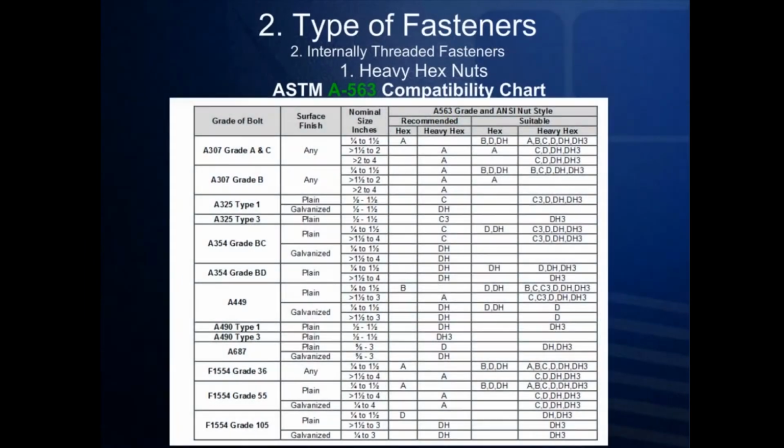Based on the previous slide and this nut compatibility chart here, things might get a little bit tricky, but don't worry, this is really for reference purposes only. What beginners should realize is that the nut that is to be used is actually based upon what bolt is being used. Nut compatibility charts like the one shown here are used to make these decisions easy.